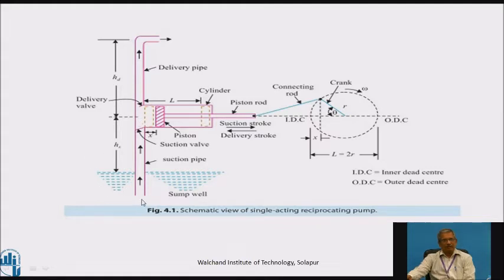Due to that, the water will be sucked into the suction pipe, which will make this valve open, and the water will enter and start filling the left hand side area of the piston. In the cylinder, the water will start filling.